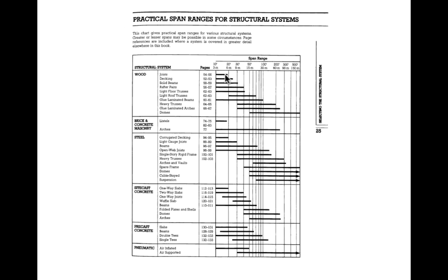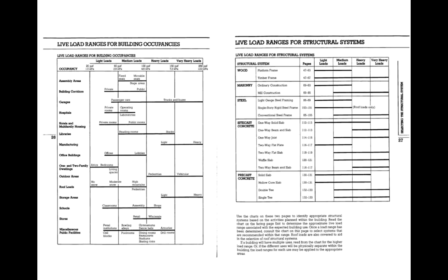And even timber, if we treat it right, especially if we use something like glue lams, they're all basically competitive in terms of the span. We can get slightly bigger spans with steel, especially if we use open web joists. But between concrete, less exotic steel items, and timber, we're all within that 20 to 30 foot range. Wood we'll often use for residential because it's so much cheaper, right? You can see that joists will span any typical residential dimension up to 17 or 18 feet.